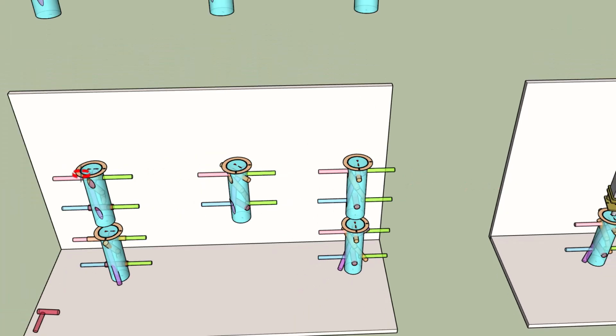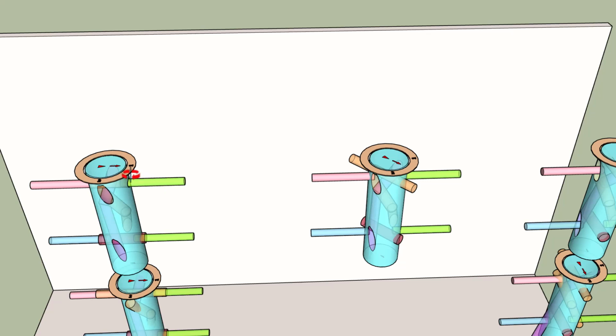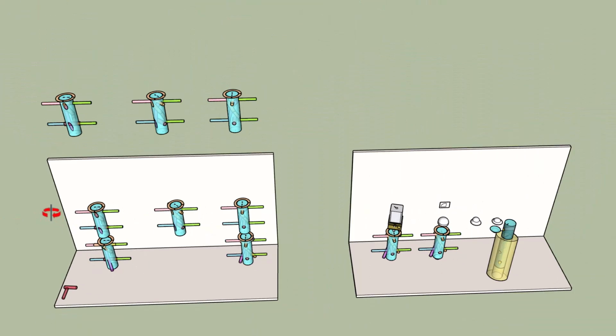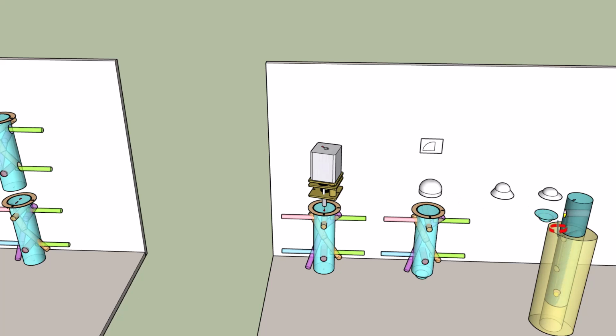But if you turned it over to here, the hydraulic cylinder would extend, because you've flipped where the pressure is and where the suction is in the hydraulic cylinder. And of course, this is a stem of metal that is press fitted into a surround of Delrin acetal. So that becomes the bushing and also the seal.